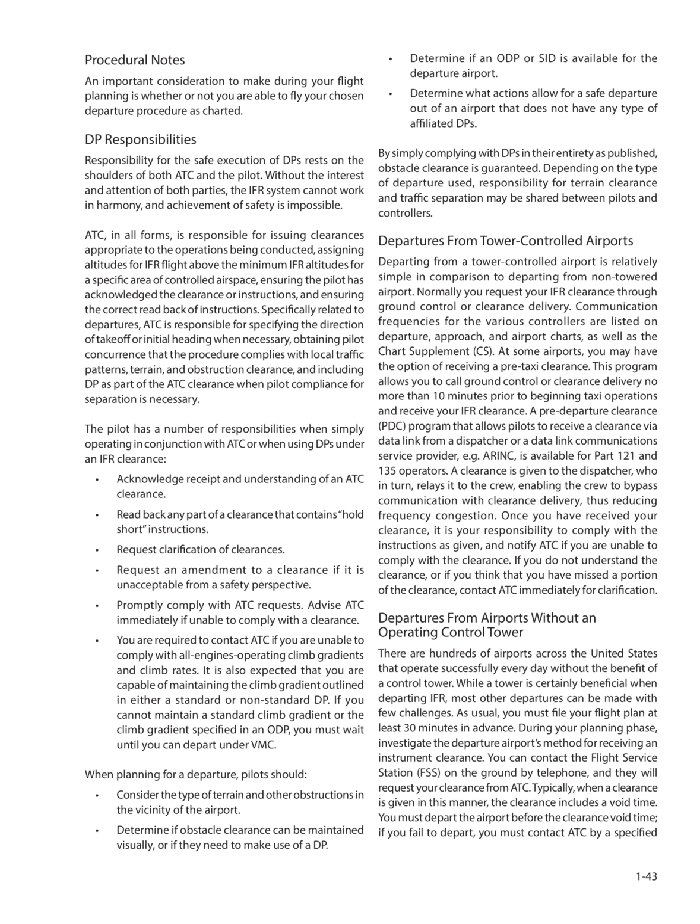You can contact the Flight Service Station, FSS, on the ground by telephone, and they will request your clearance from ATC. Typically, when a clearance is given in this manner, the clearance includes a void time. You must depart the airport before the clearance void time.